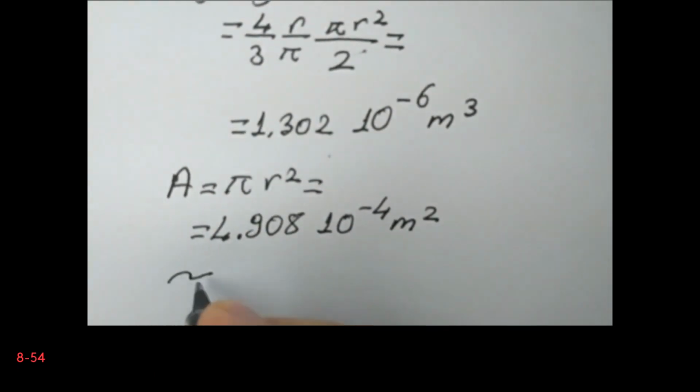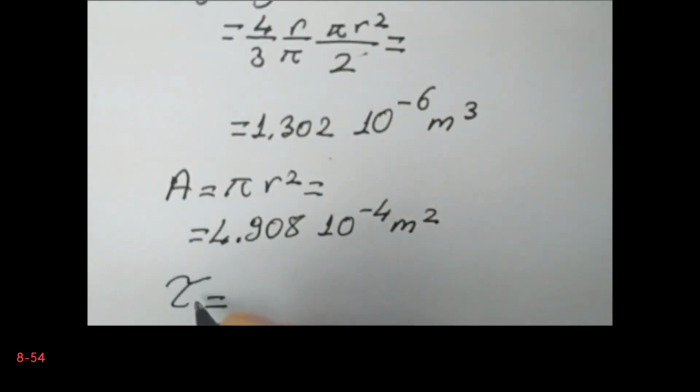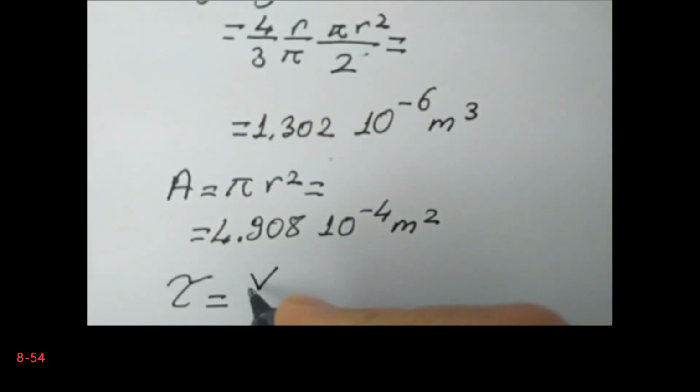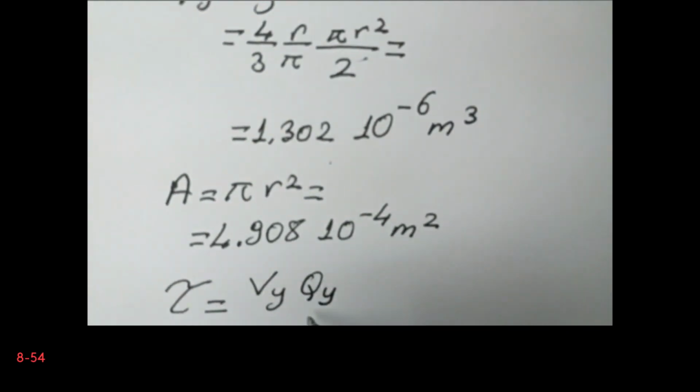So the shear stress for this particular location is, we have shear caused by the Vy, so Vy multiplied by Qy divided by Iz multiplied by the thickness.